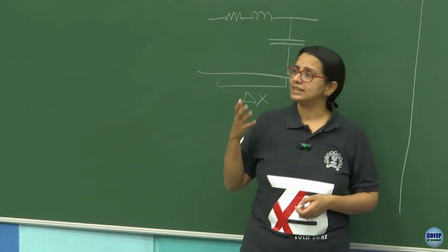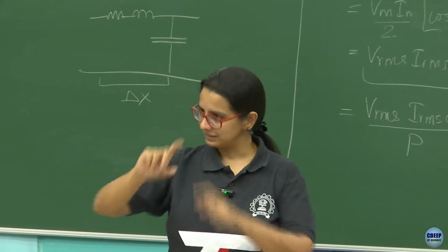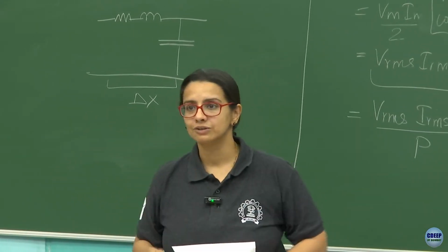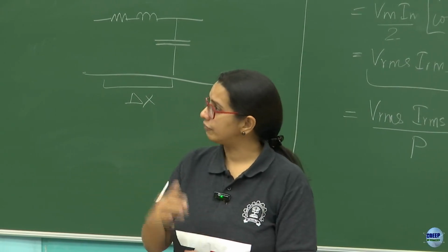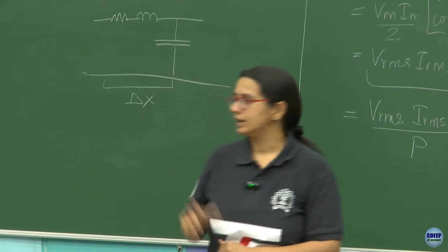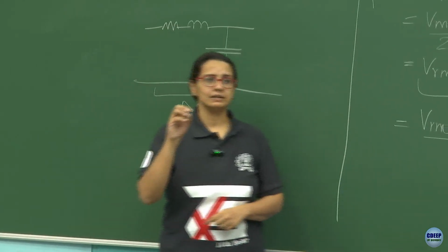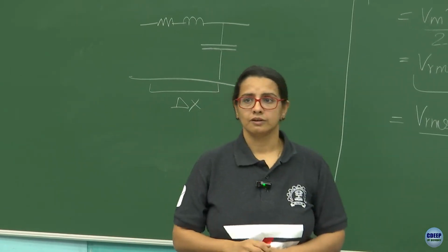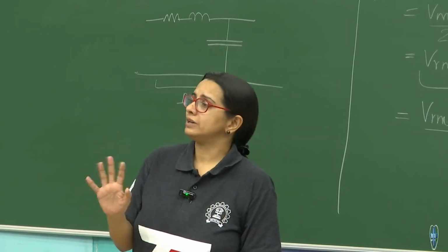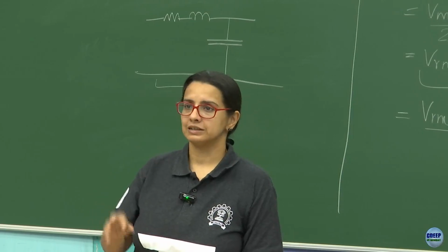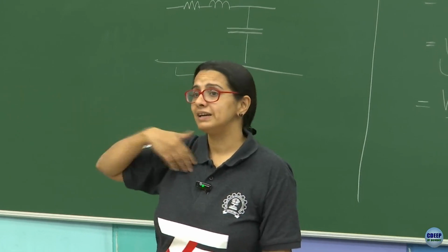And that's what power quality standards would dictate. Power quality standards would say you have to try and give him the voltage within some margin of error. You would have to be around 220, 230, 240 volts, whatever is the reference for us, nominal voltage and nominal frequency, correct? But is it really possible for that utility, without doing any active measures, to continue to just maintain 220 here, independent of how I consume?